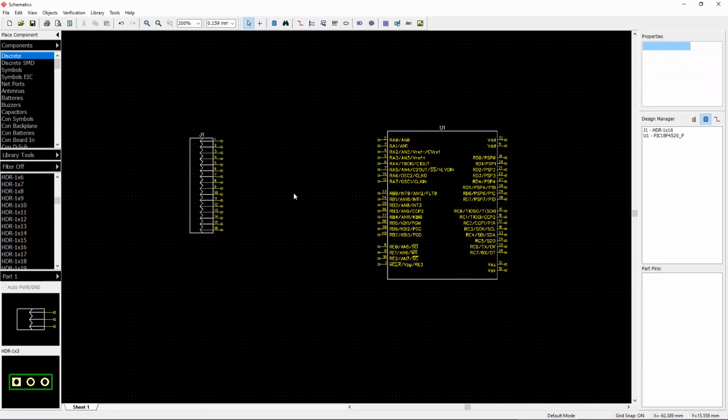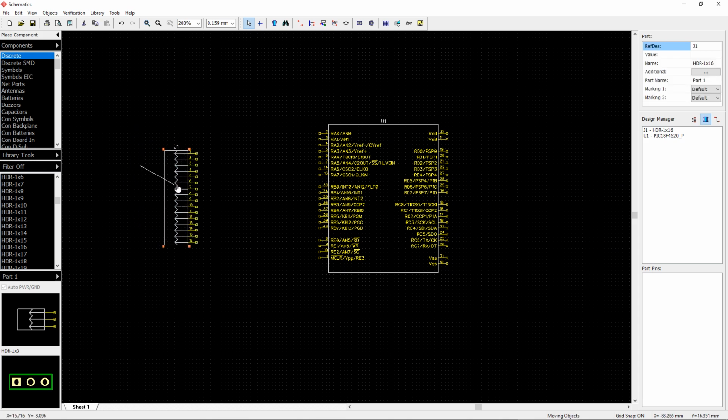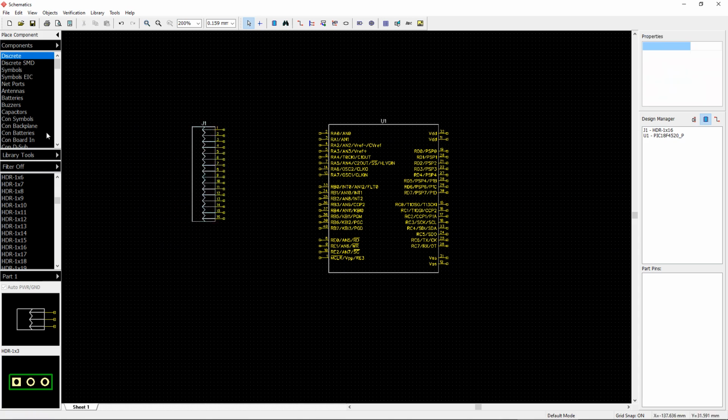From our LCD, we know that pin 1 is ground, and pin 16 is also another ground, for the backlight of the LCD. First, let me bring all the components that are necessary, then I'll join them later. The next thing we want is the voltage regulator.